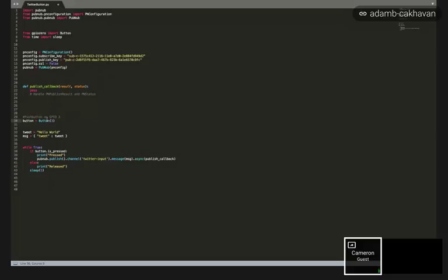And debouncing is, what that means is if you push a button, it's not actually pressing itself once. It's pressing itself about 20, 30, or 100 times in the span of milliseconds that you would never be able to tell. And this is because when you're pushing a button, it's going to be on a microscopic scale vibrating against the metal. And that's just going to be triggering the metal, the button, the sensor, about 100,000 times in a second. And you don't want that. You don't want, when you press a button, to send 1,000 tweets. You do not want that to happen.